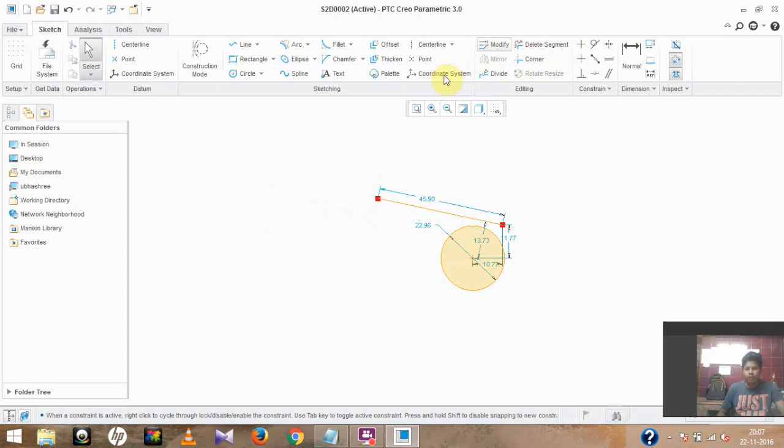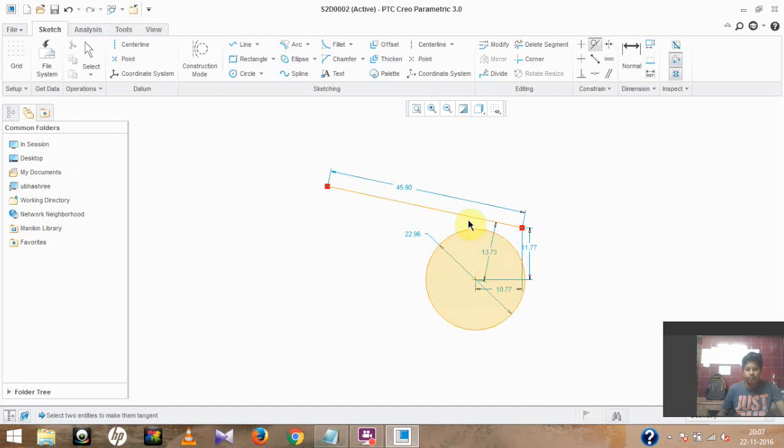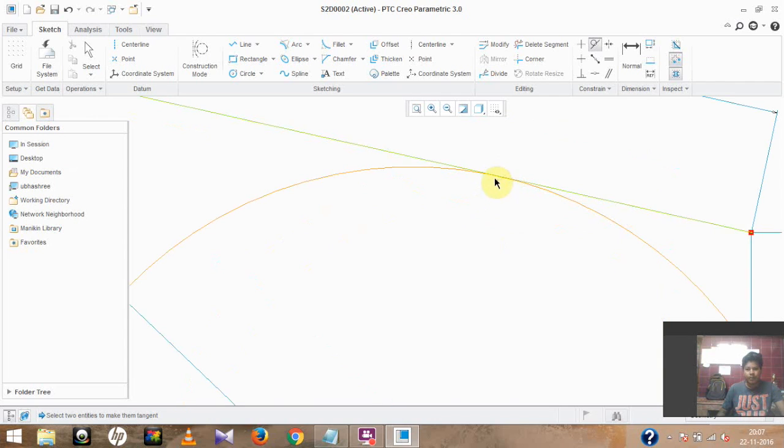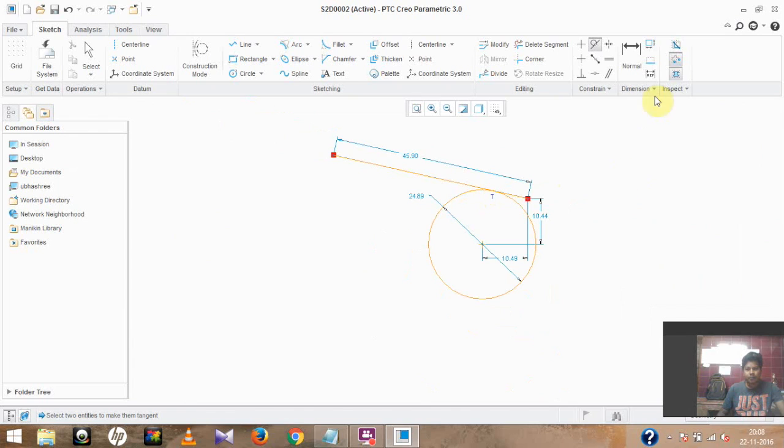We are going for defining some mathematical relations. Select this icon. As you can see, the icon itself is showing a relation between a line and a circle. So click that one. Select first the line, second the circle, and it will automatically take the tangential. You can see over there it is also written T, that stands for tangential. Similarly, these two options come while we are drawing the figures. Let us move to the next option. This is normal.